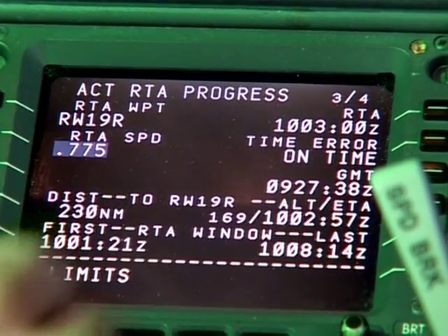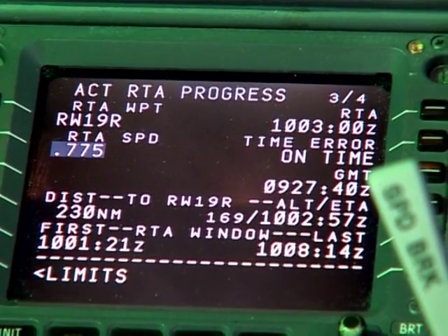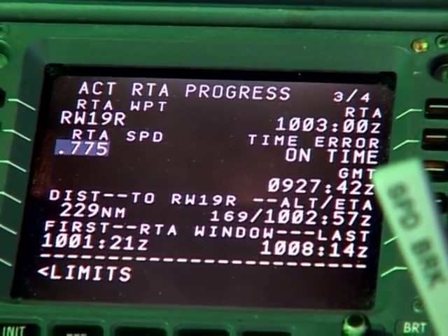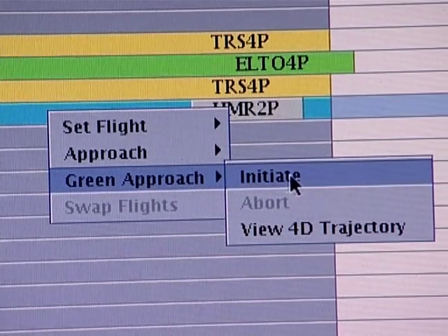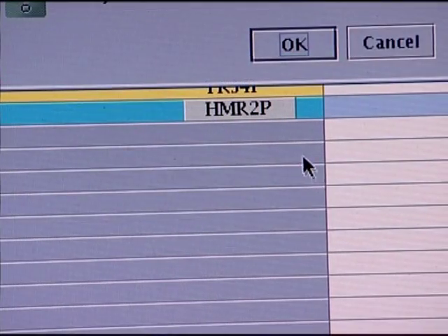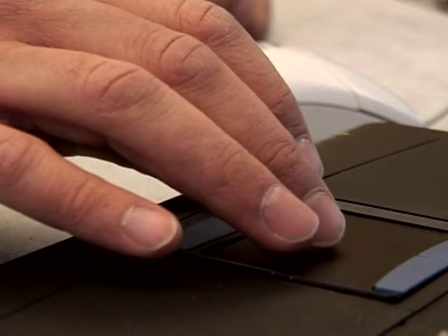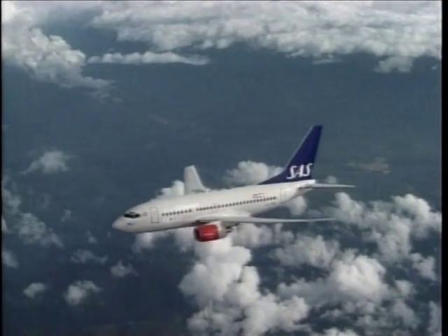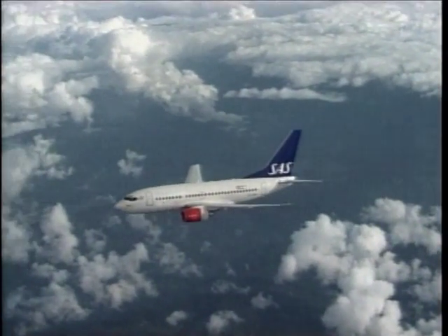If you come up with a constraint, with altitude, time or anything, the pilots will insert that in the flight management system and the controller will then see the result of that and see how that fits into his overall planning for the airport. So by doing that, we can utilize the control authority that we have with the aircraft. Basically for a 1 hour flight, we have 6 minutes that we can work with. So we can come a bit earlier and a bit later to the airport.